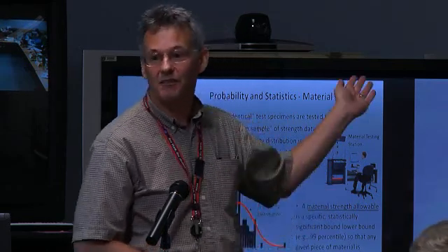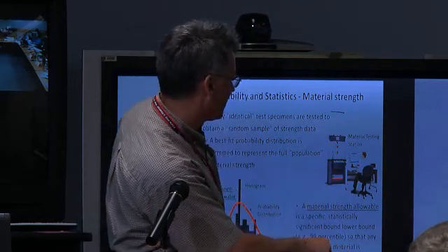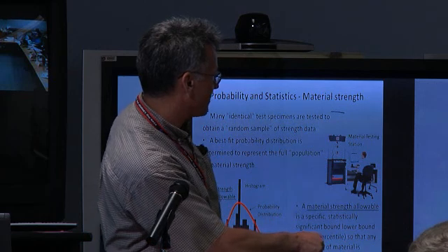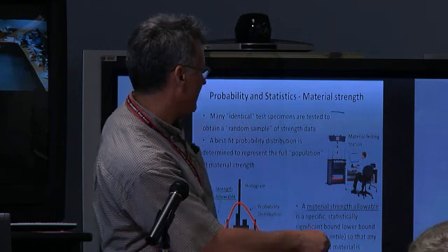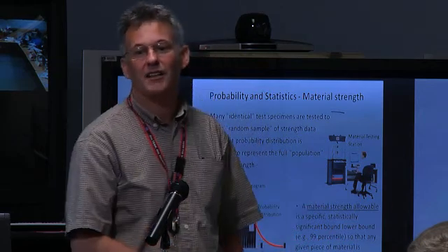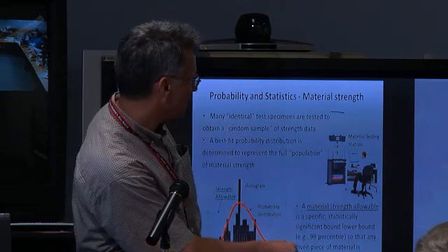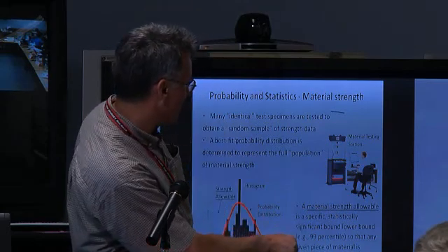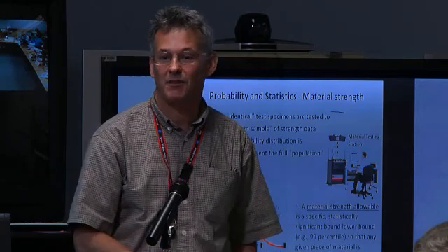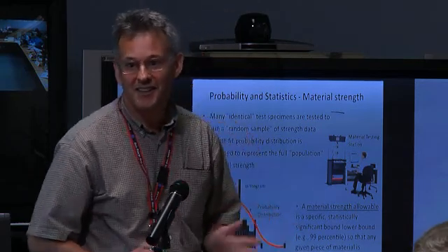So let's say we're going to use that to design a bridge. Okay, so we've got data from 26,000 pounds per square inch up to, looks like, almost 55, 56. So where in there should we design the bridge? If you ask your students this, they may say, well, most of them broke there in the middle, so right around let's say 37,000 pounds per square inch. So that's great. So every other time you drive on that bridge, it's going to collapse under you. So that's probably the wrong answer.